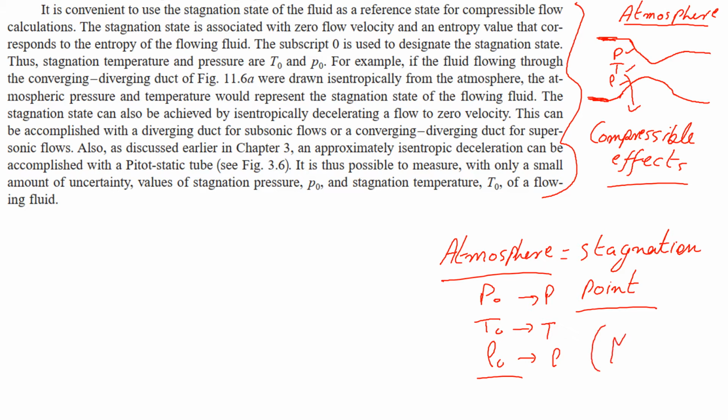Also in relation to the Mach number, that will tell us what will happen if our flow is subsonic and that flow is entering into the nozzle. So what will be the effect on pressure, temperature and density then, and if it is supersonic, then what will be the effect on these state functions.